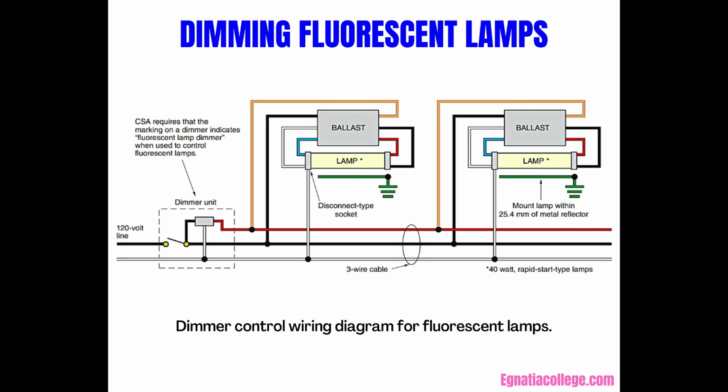However, some compact fluorescent lamps have an integrated circuit built right into the lamp, allowing it to be controlled by a standard incandescent wall dimmer. These dimmable compact fluorescent lamps can replace standard incandescent lamps of the medium screw shell base type. No additional wiring is necessary. They are designed for use with dimmers, photocells, occupancy sensors, and electronic timers that are marked incandescent only.